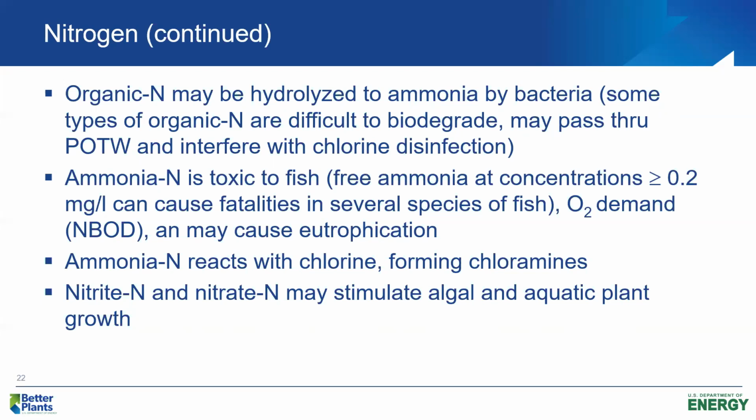But we're concerned about the ammonia, but we're also concerned about the organic nitrogen because most of the organic nitrogen will be hydrolyzed to ammonia by the bacteria, the BOD removing bacteria in the activated sludge process. So most of the organic nitrogen, by that equation I showed you in the very first slide, gets converted into ammonia nitrogen. Okay, so very concerned about ammonia and organic nitrogen in raw wastewater.